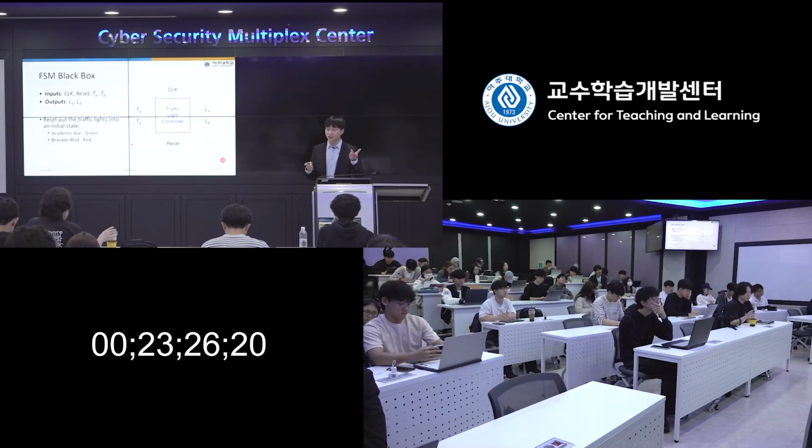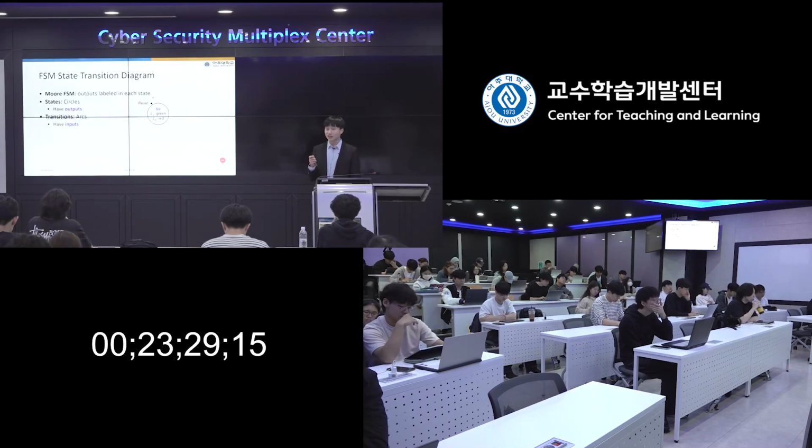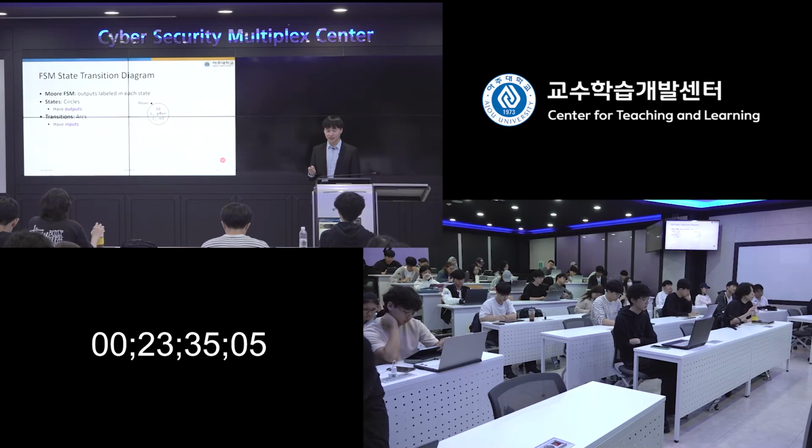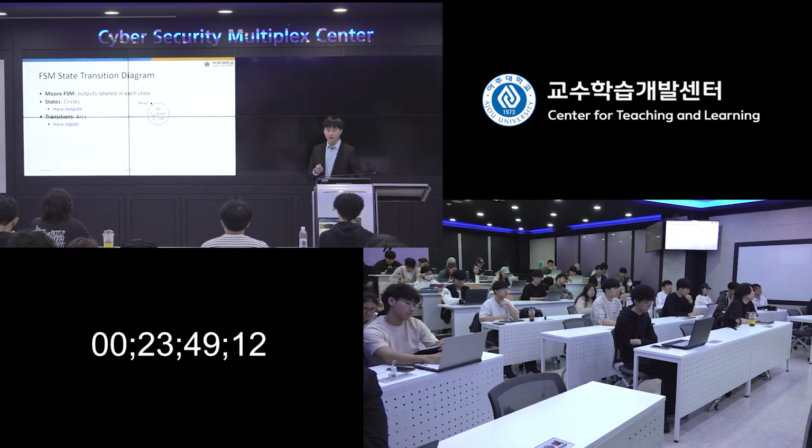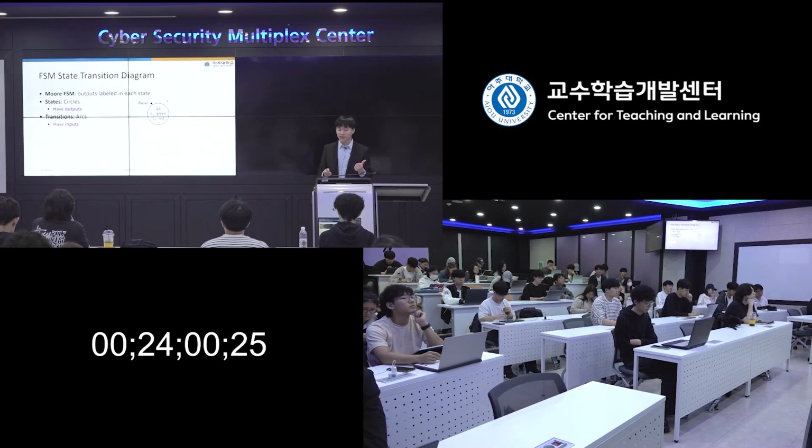Now based on that logic, we first build our state transition diagram. We start from the initial state, which is S0. We use S0 to represent the initial state. Particularly, when you design a state transition diagram, you put a circle, and inside the circle is the state number. The other information is the output. For example, here RA and RB are the output for this state. Then transition information or conditions are the input. They will be tagged on the arcs or arrows.